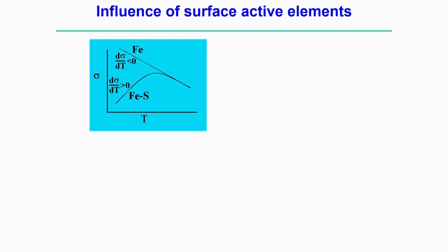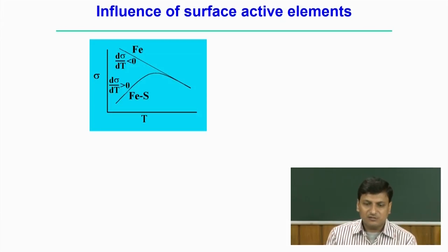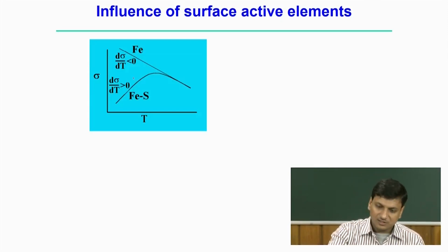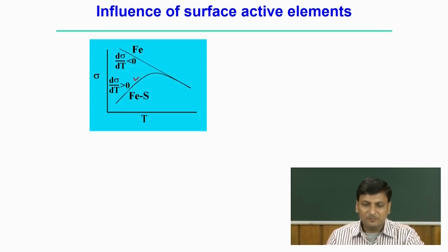So, theoretically, when we use some surface active elements within the metal or during the welding process, here you can see the temperature coefficient of the surface tension plotted like that. It can be negative, or reach some optimum point, or maybe follow the negative slope. In the first figure, the temperature coefficient of the surface tension, the gradient over this graph is greater than 0, that means a positive slope, reaching towards the optimum point and then gradually decreasing.